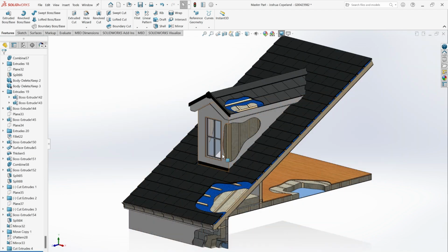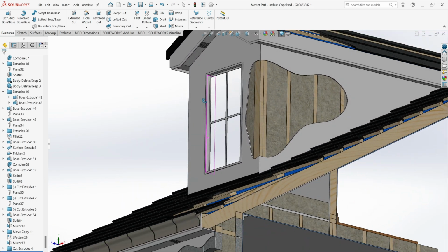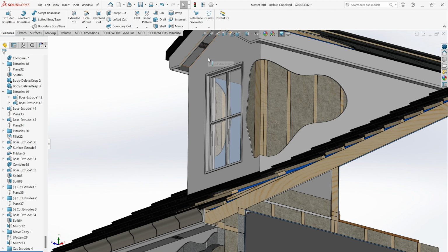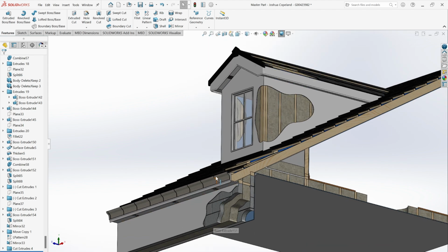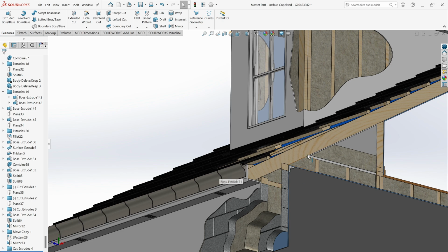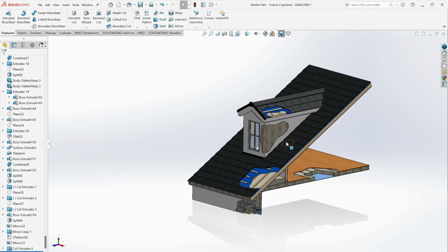It is essential that the roof is equipped with adequate ventilation. This is to avoid excess moisture and condensation buildup which can cause damp, mould and structural damage.